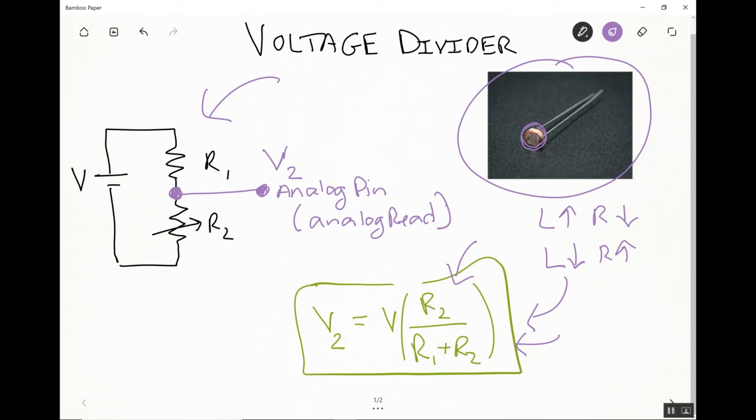All right, so those are two examples of applications of voltage divider circuits for hooking up an analog sensor, in this case, the photocell sensor. In class, we used an analog sensor, the temperature sensor, and whether you realize it or not, we hooked that up in a way that set up a voltage divider circuit, and we measured the voltage that was being used by the temperature sensor. We also looked at the example of a voltage divider circuit in the context of designing a circuit to make an LED work with the proper voltage and current so it lights up but doesn't burn out.